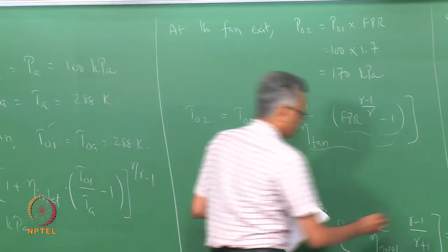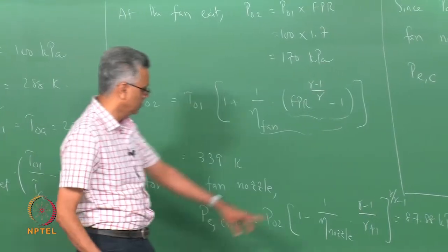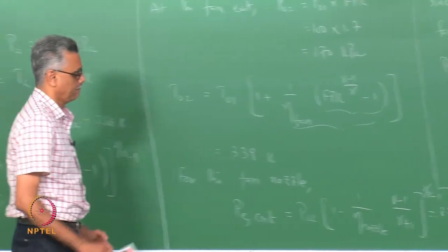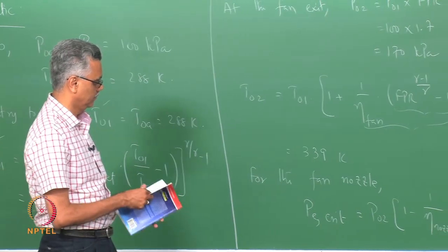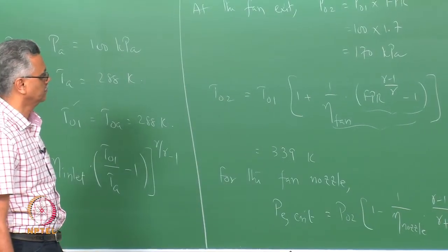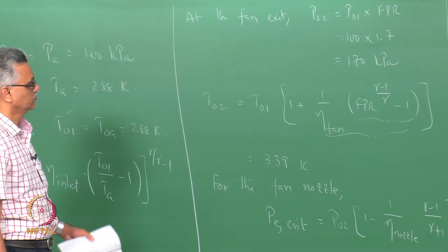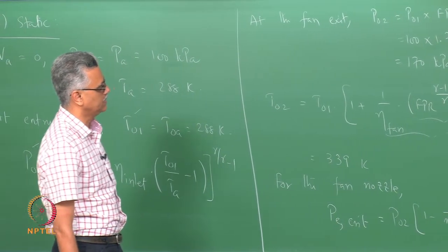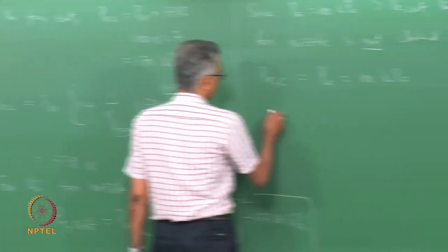Oh yes, thank you. So this has gamma over gamma minus 1. Yes, thank you. So please include that also. So there is an exponent here, gamma over gamma minus 1. So I know the exit static pressure, I need to evaluate the exit velocity or the exit static temperature, any one of those things would do. So let us calculate the exit static temperature.